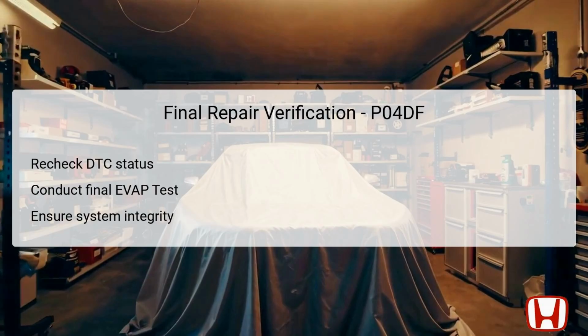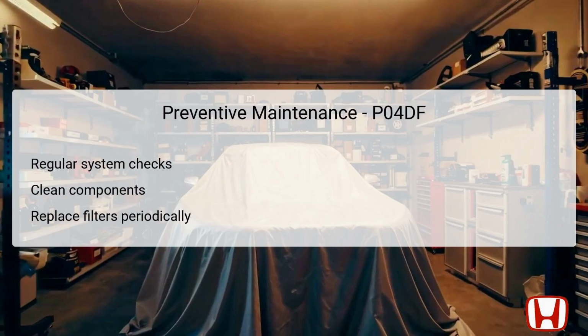specifications and compliance standards. Implementing preventive maintenance can significantly reduce the risk of encountering issues like DTC P04DF in the future. Regular system checks should be conducted to identify potential weaknesses within the EVAP system before they lead to larger failures. This includes visually inspecting components such as valves for wear and tear.